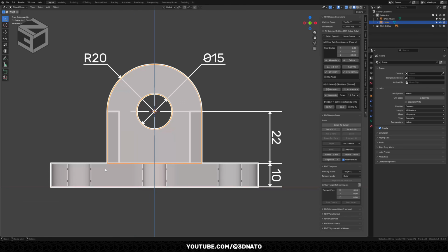Now let's rename this mesh and place it into a Boolean collection. Press F2 to rename and call it bool+.001. Then press M to move to collection, new collection, and call it bool+. And since we don't need to see this collection on the viewport, exclude from view layer.